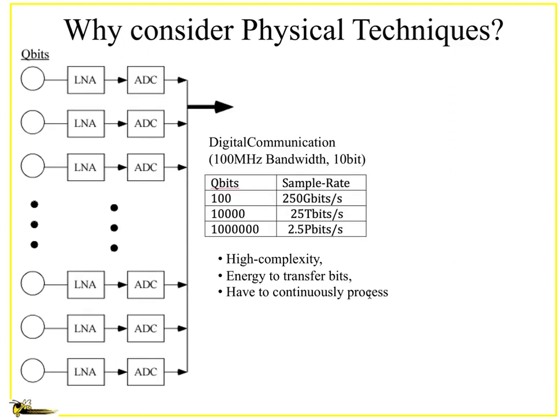So you might just say, well, fine, just put a bunch of analog to digital converters. I'm sure those are near free. Well, they may or may not be, depending on how you look at the world, but you can often do a lot of them. Say you put 100 megahertz ones and run them at 10 bits. Well, what you end up finding is that, if I had 100 qubits, the amount of data that needs to get transmitted is probably around 250 gigabits per second. That's quite a bit of data for what is a relatively small problem.